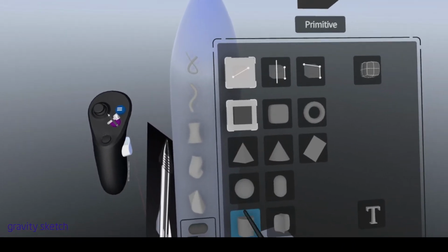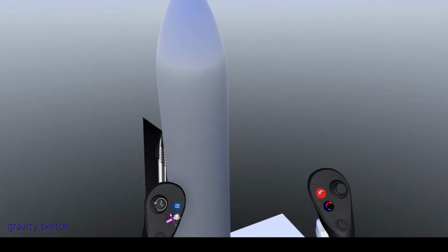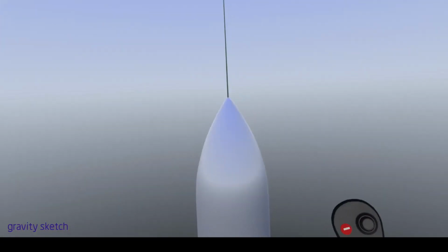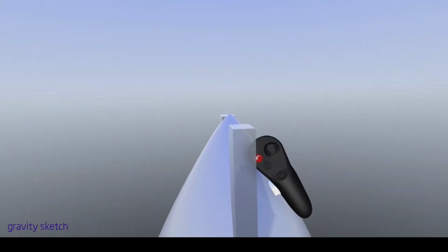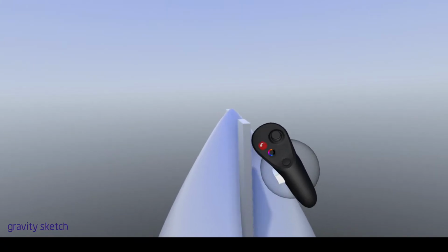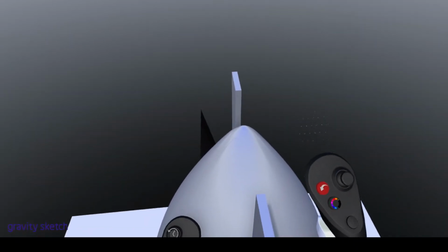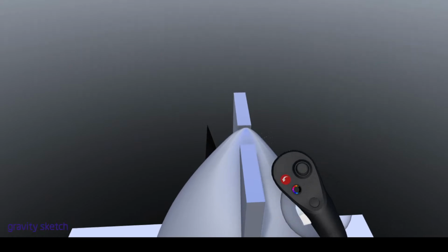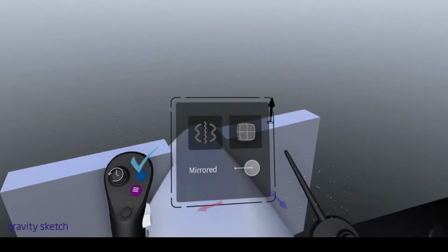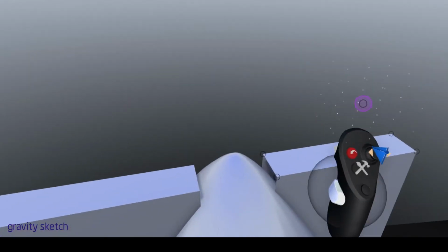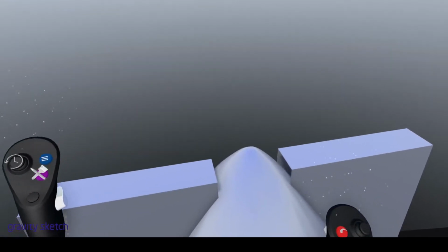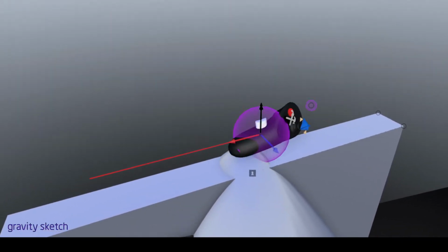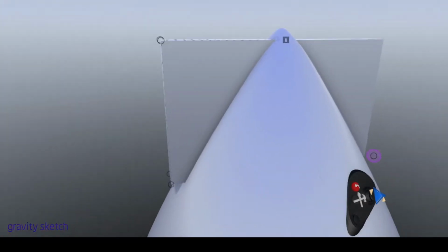And then we're going to create a cube. Make sure we have the correct material selected. And we're going to turn our grid on. Yeah, there we go. And so what we can do is we can convert this to a sub-D object, delete those faces, and turn grid off now since everything's aligned, and merge these pieces together.